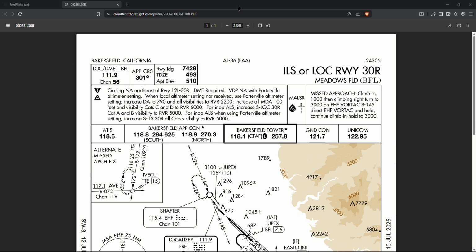So, some main information that covers, so let's go over the name. For this, ILS localizer runway 30 right. If there are multiple, they will be in alphabetical order backwards, so Zulu down to Yankee. With that, I guess you could say, the closer to the Z that letter is, the lower the minimum is going to be. Which is important because if you're flying in terrible weather, you want those lower minimums to be able to reach that airport and have the best odds of landing.